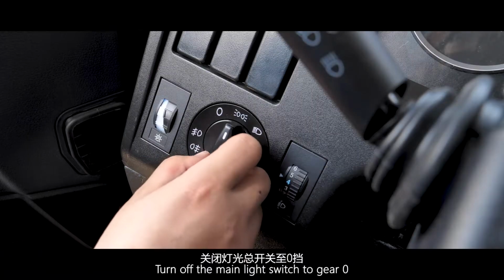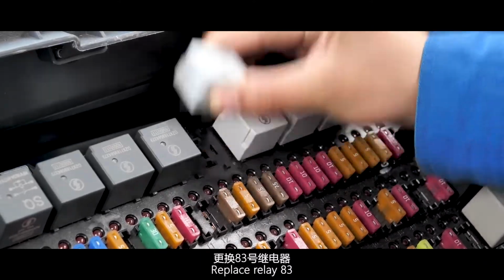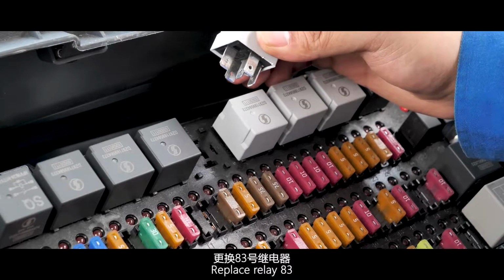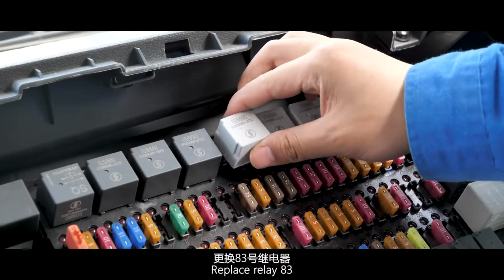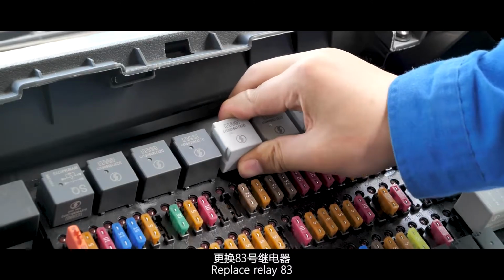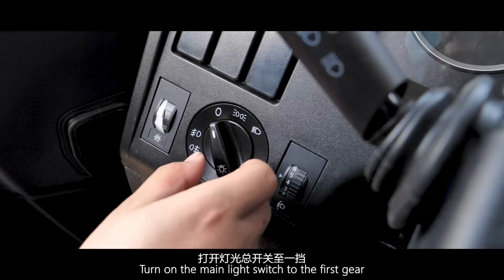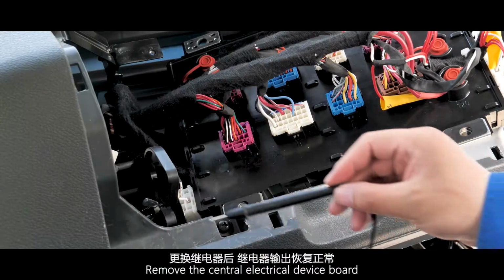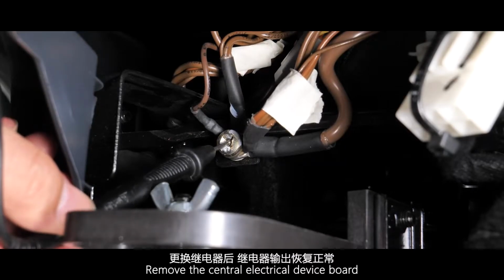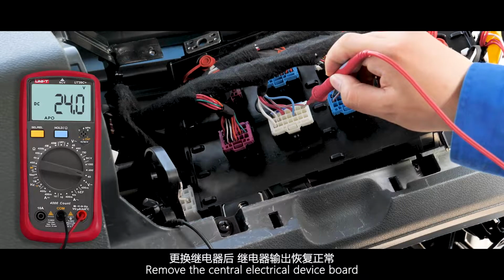Turn off the main light switch to gear 0. Replace relay 83. Turn on the main light switch to the first gear. After replacing the relay, the output returns to normal.